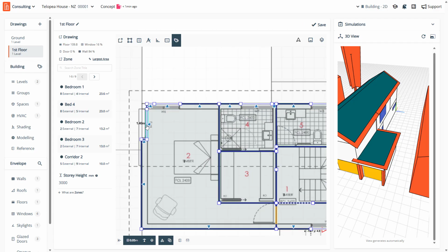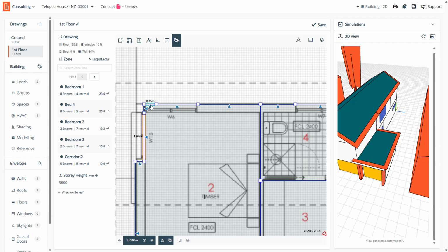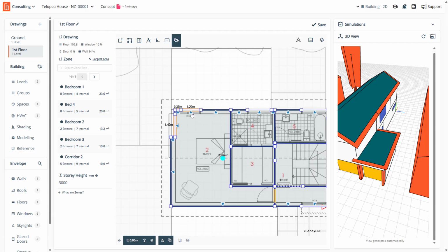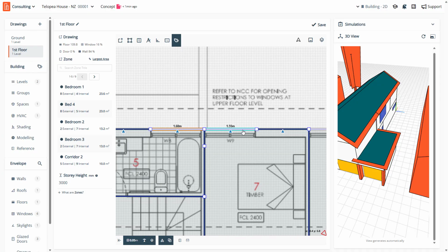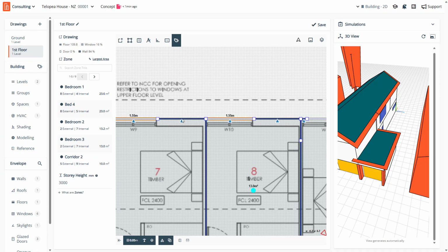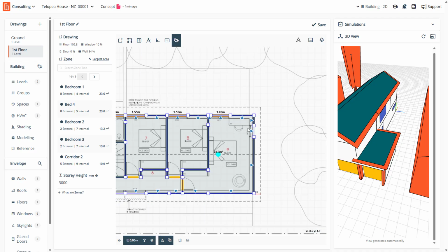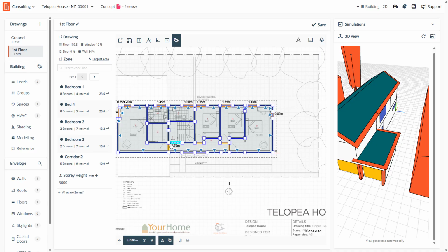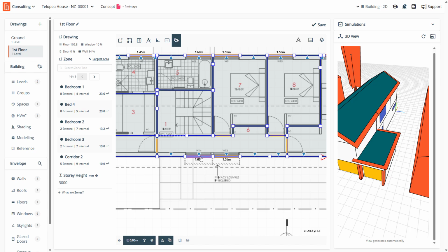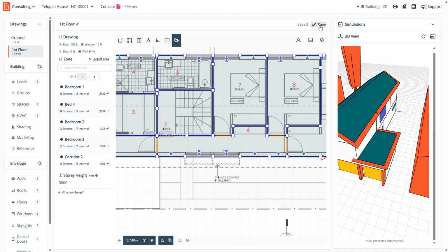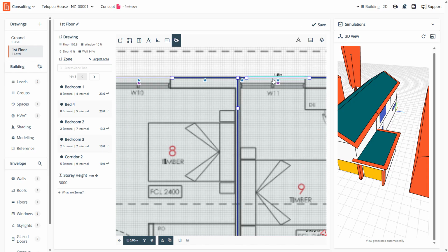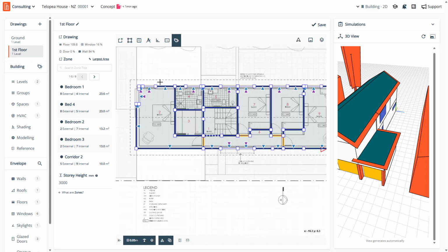And now what I've just got to do is step back over this one more time here because I've removed the tags for the window. So tags can always double up. I'm just zooming in and zooming out, selecting each one. No big deal. And those are now selected, and now we can double down on those tags and bring in that tag there, W6 to W15, to represent those windows. So those are now all in there. I think that's fine, happy with that.